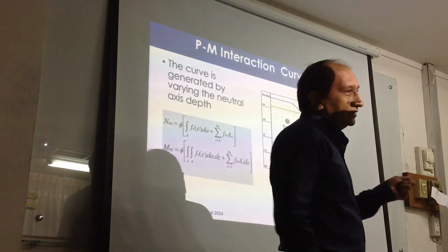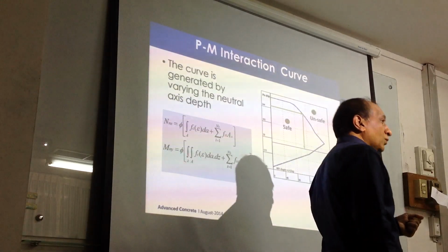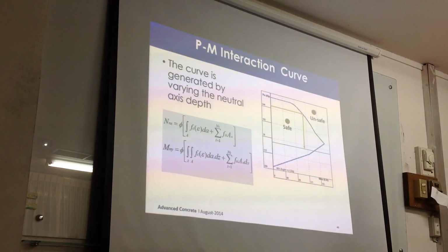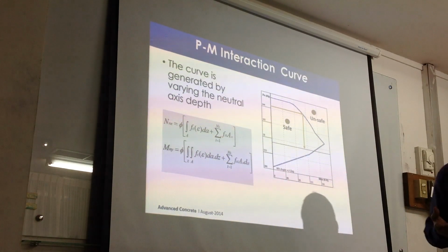The problem is that we are dealing with earthquakes, dynamic loading, and it's changing all the time. In a typical earthquake, which lasts about 30 seconds, we have about 3,000 variations of the loading. For every variation, you get one loading. So 3,000 values of changing moment and load in one earthquake. Then you need to combine it with other load combinations, with positive dead load, negative dead load, with live load, without live load. You end up with 10 to 20,000 easily.